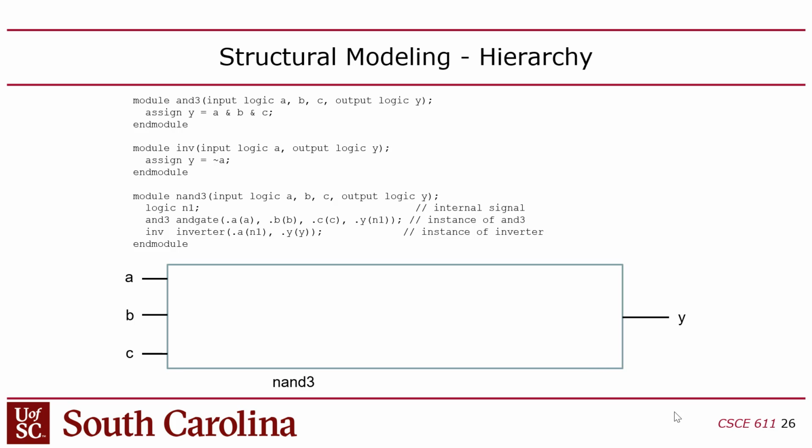So the simulator will create a design tree, a design hierarchy, and it will use those names in there, but they don't actually translate to anything in the physical target, the implemented design, right? These are only there for human purposes, because when you synthesize it, it gets flattened, all the hierarchy gets flattened out.